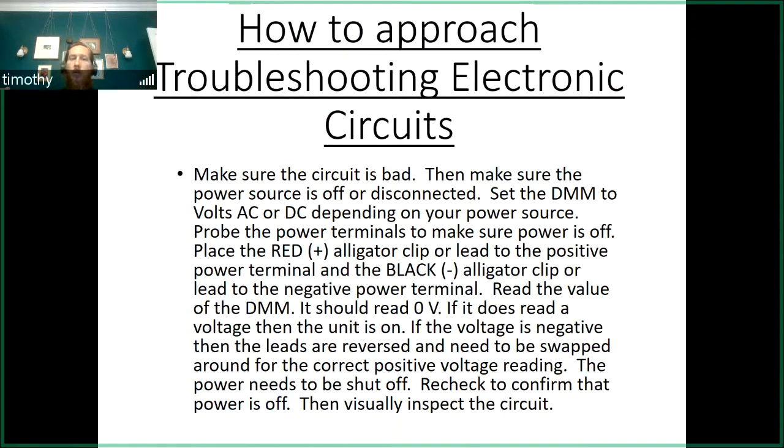So you can just go through and do a continuity check and make sure that your ground is not connected to 5 volts. Make sure your 5 volts is not connected to 12 volts. Do all those types of checks and just make sure that you have double checked your voltage and your ground planes at least before you turn on power. When you turn on power, connect it, turn on power, let it run for just a couple of moments and then turn it off. You want to then inspect your circuit and make sure that you didn't burn out any traces and that none of the pieces are getting hot because they will physically burn out.